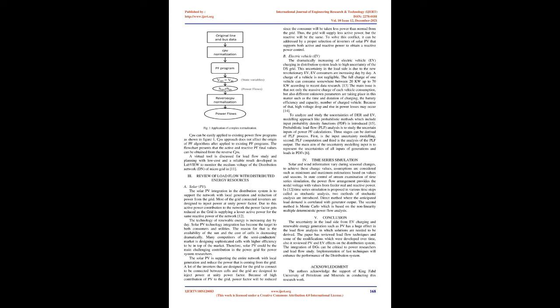Modified versions of load flow techniques have been introduced by researchers along the way to overcome and tackle the ill-conditioned problem. A load impedance matrix, LIM, derived from conventional forward-backward sweep, FBS, method to calculate the bus voltage in a single step, whereas conventional FBS requires 2 steps to perform the same. For the sake of enhancement of fast decoupled power flow method, a complex per unit normalization, CPU, was discussed. The CPU concentrates on the use of volt-ampere, VA, base to overcome the numerical problems caused by high R/X ratios of the distribution feeders. As a result, FD power flow makes it simple and effective for the power flow analysis.